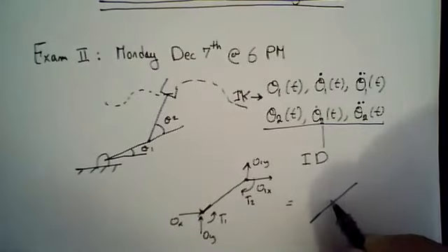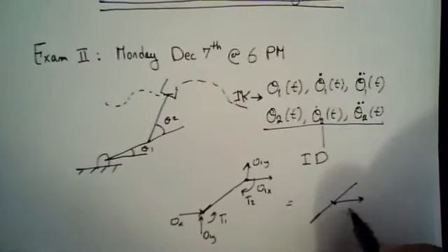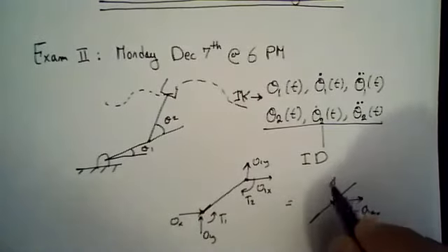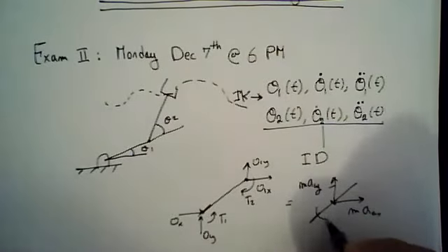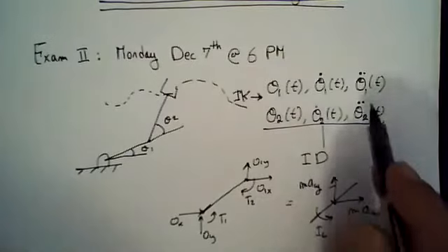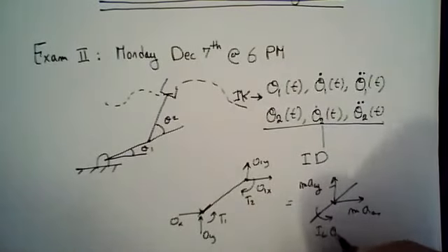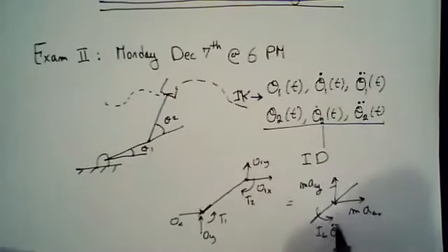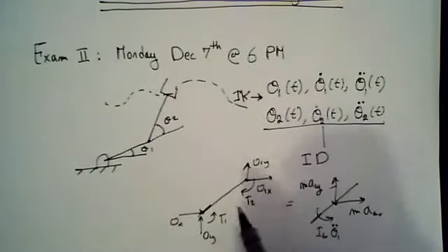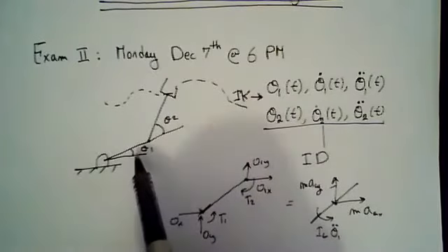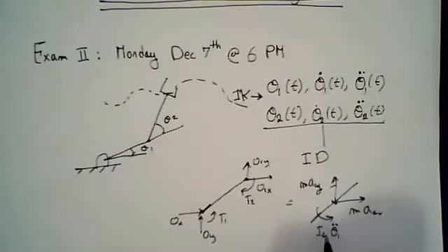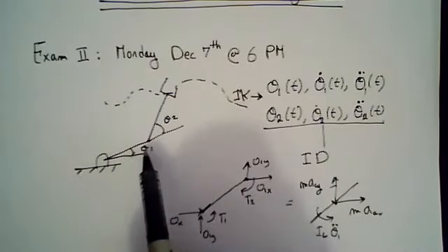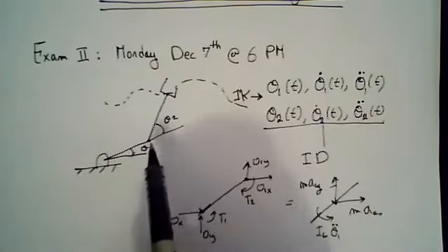So basically at the center of gravity here, we're going to have m a_gx, and then we're going to have m a_gy, and we have I_g alpha 1. Alpha 1 has to be theta 1 double dot. So here, be very careful that theta 1 double dot, or the rotational inertia, is always in the same direction as the growth direction of theta. So this is my theta, this is a fixed line, so theta 1 is going to be increasing like that. So you always have to put this rotational inertia moment in the same direction as the increasing direction of theta. Same thing for link 2.